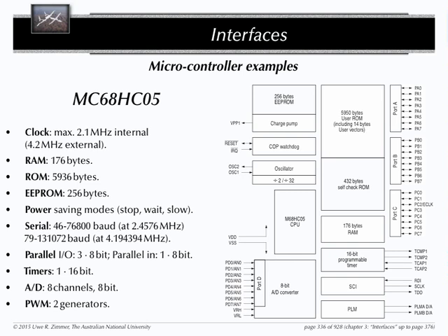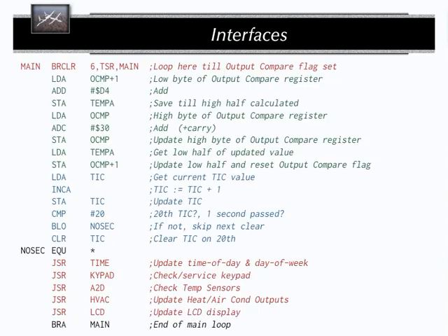As you were quite limited in those kind of environments, no, these things were not programmed in Ada, but they were mostly programmed just bare in assembly. And classically, this is what it looks like to program these things in assembly, not even using any kind of an interrupt. Using busy waiting, polling. The very first instruction, branch until a certain output flag is being set to 0 or to a certain value. And you're just looping on the spot.